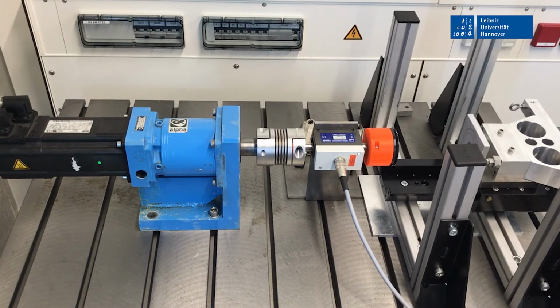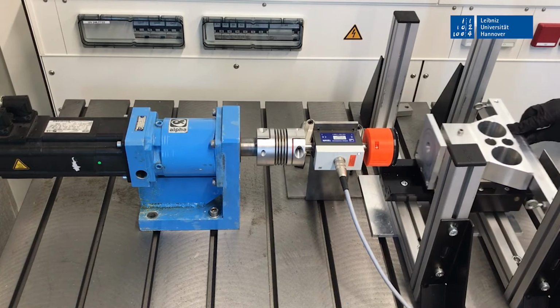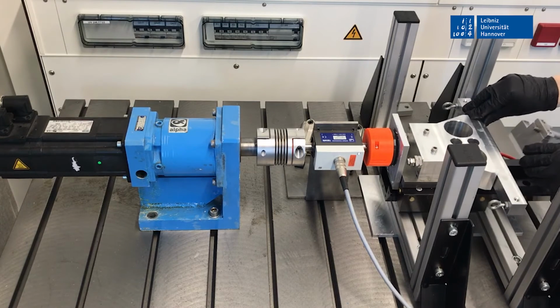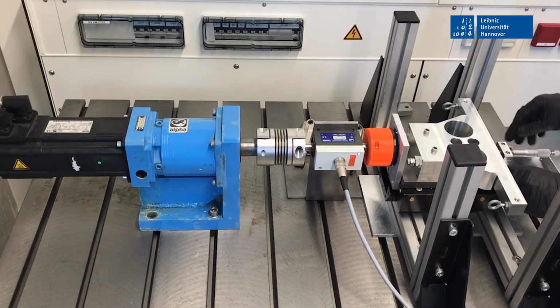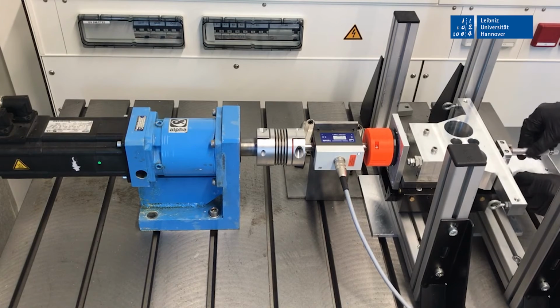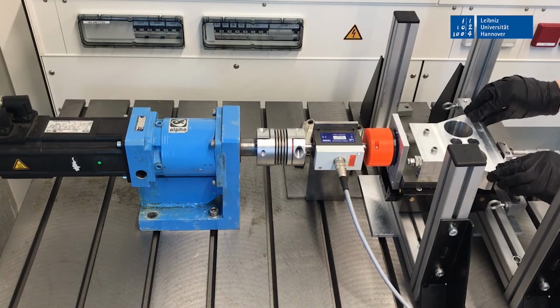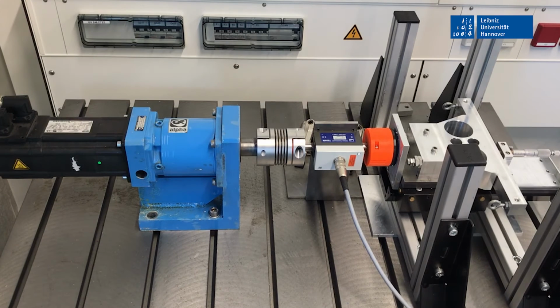A running-in procedure, which is performed at the highest velocity to be analyzed, is performed to condition the rubber sample and ensure constant fluid film thickness in the dynamic contact. Finally, the actual friction measurements are performed, whose target value is the frictional torque as a function of the fitted width and the rotational speed of the seal.